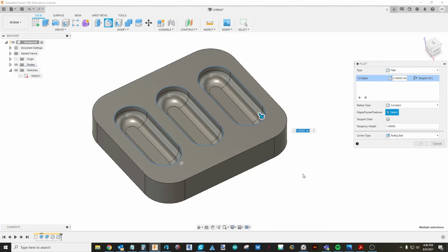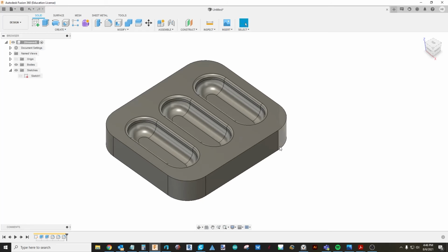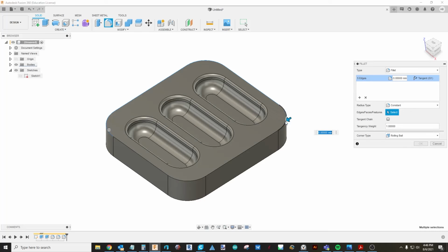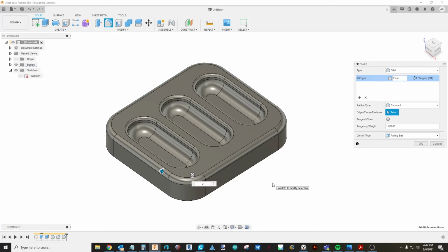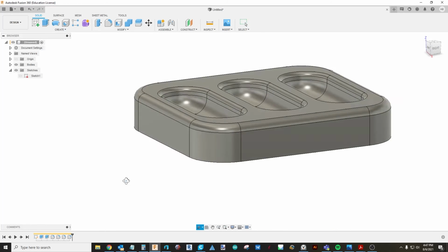This is unneeded, but makes it look a little softer, a little nicer. So we can try like a 1 right there. And then we can even add a fillet to this outer edge. Let's try 2 millimeters. Cool. All right, so now I just decided I want this fillet here also to exist on this bottom face.